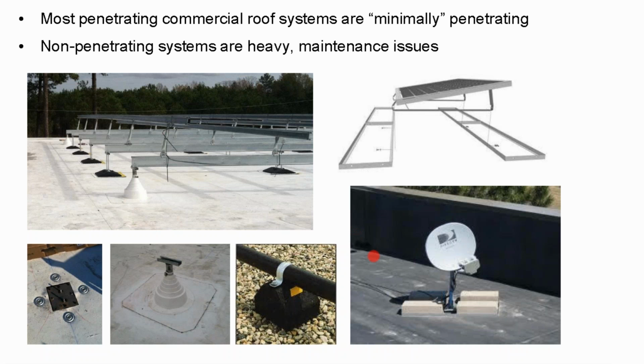Well, there's actually some more issues with that. The alternate, other than positively attaching into the rooftop, is to weight the system down with concrete. But the problem with these concrete systems is twofold. One, they usually only sit an inch or two off of the roof deck. So if you're getting pooling water on your rooftop and you get an inch or so of water, you can start getting kind of a low profile solar array sitting in water.